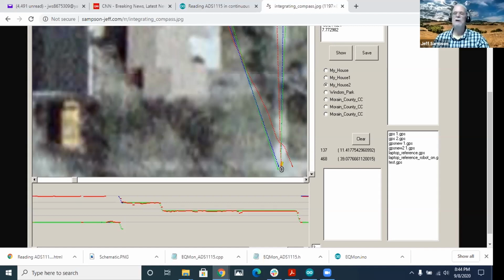And another question, I don't know if anybody's played with this, but if you have a magnetometer, I know the gyroscope and the accelerometers always have multiple sensitivities you can set. They'll say the accelerometer is like 1, 2, 4, 8 G's or something. You can pick the range you want to set it at, and the gyroscope is usually like 100 degrees per second or 200 or 2000 degrees per second. I'm just wondering if the magnetometer has a setting like that. So I'm wondering if you just set the sensitivity of the magnetometer down, if it's going to ignore a lot of the stuff that screws up everything. So that'd be another thing to experiment with.